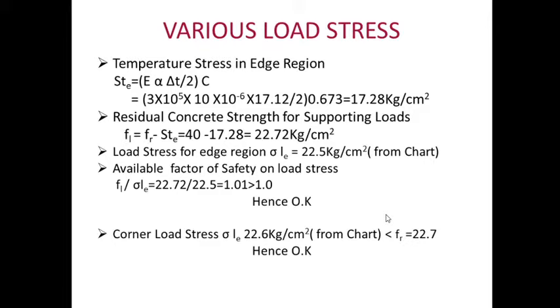So we have to find the residual concrete strength for supporting load, FL, which can be determined by FR minus the loss of concrete strength due to temperature stresses, STE.